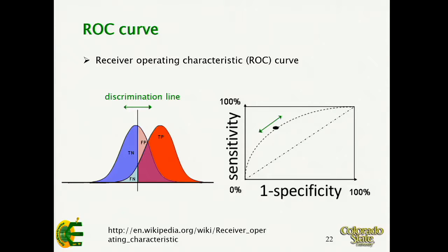The upper bell curve, shown in red to the right, is what the distribution of readings is if there's a positive. So let's say that this is a cracked jet engine blade, and this is a fine jet engine blade, not cracked. And in terms of the signal strength of the ultrasound that comes off of that inspection, we're going to get different levels of reading.